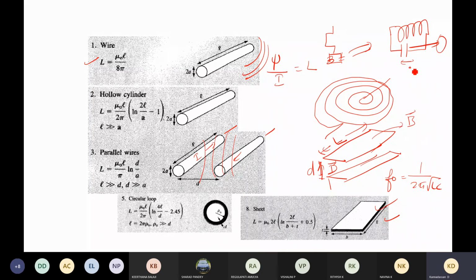In this way you can change the capacitor, and the same knob can be used to shrink and lengthen the spring part. So you can simultaneously tune L and C. When you change L and C, you change the resonant frequency, and in this way you can select a particular station. This is how in very olden days people did it, without the knowledge of any computer or mobile phone. They beautifully designed extraordinary systems, including wireless and wired systems.